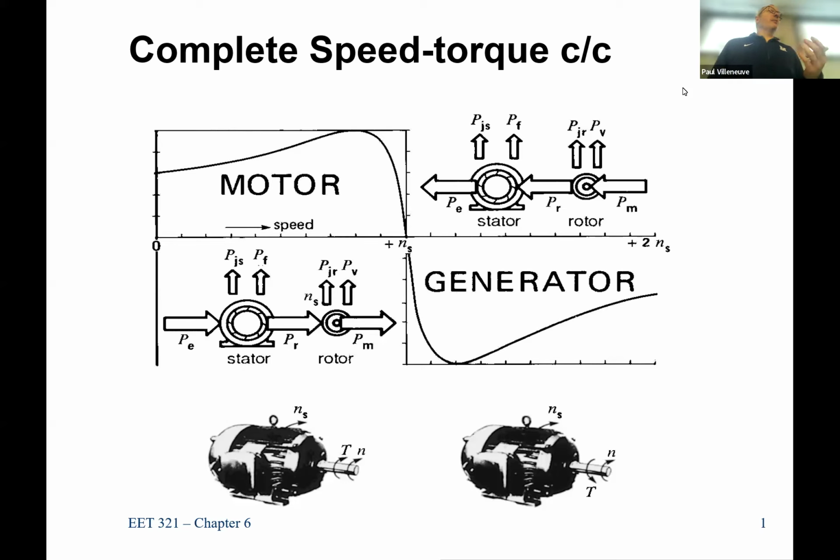So remember we talked a little bit about wind turbines way back when? So wind turbines use doubly fed induction generators. They use an induction generator, but you actually provide an AC voltage on the rotor circuit to kind of add or subtract. So it's not a true induction machine. That's why it's called a doubly fed induction machine. But the reason why that's able to work is because they're interconnected to the grid. So that's the only way a wind turbine works, is actually interconnected to a grid that is energized.